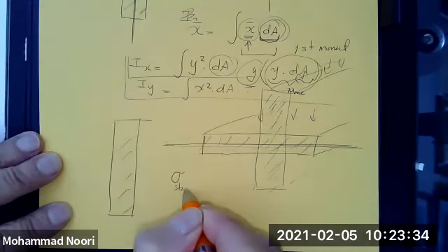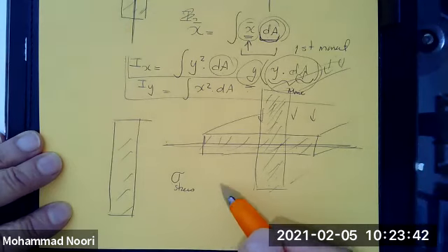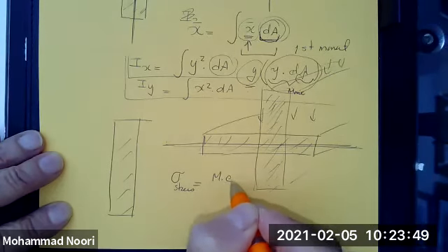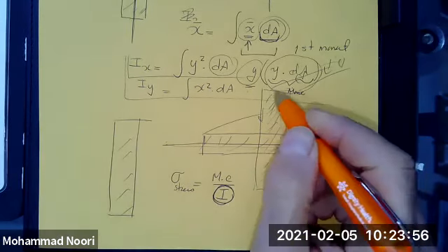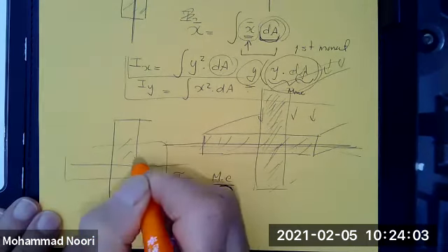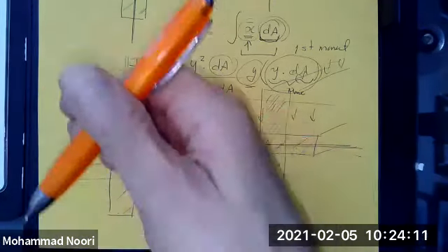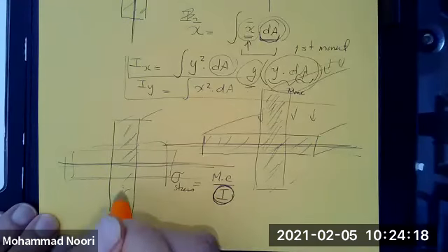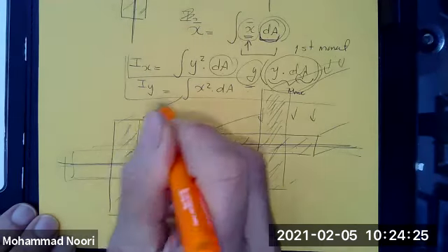We want to find the stresses, which are the intensity of the load, the distribution of the load inside this structural member. These are inversely proportional to the moment of inertia, or the second moment of an area about this axis. So if you look at it this way, if this area is located like this, its area is far more scattered about this axis than this one. So it has a larger moment of inertia. Therefore, its bending stress would be less. That's why we put those pieces of timber like this.